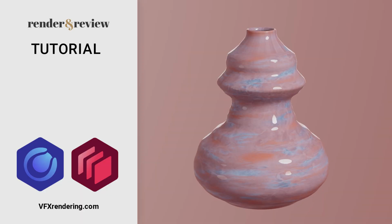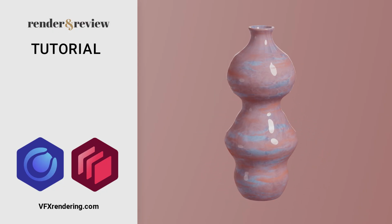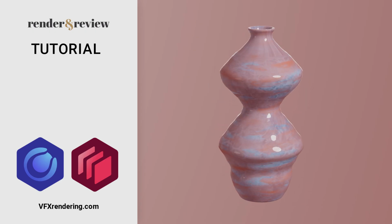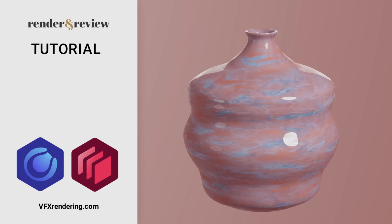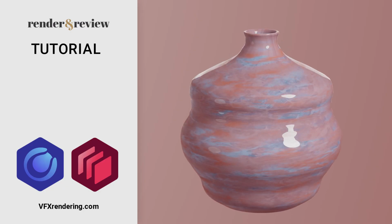That brings us to the end of this tutorial. In this video, we've gone through the process of creating an animated pottery effect in Cinema 4D using the Spline deformer, together with the Spline to Mesh generator. Starting from a simple spline, we added procedural deformation and noise to create natural motion, then converted that movement into a fully formed 3D clay pot.